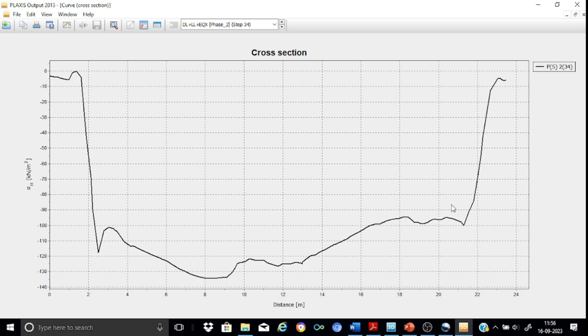So this is how we need to interpret the results in terms of the stresses as well as the settlements for the various phases, and then find out whether these calculated values match with our design regulations. If not, we need to change the various parameters, for example, the raft dimensions. We also need to inspect how to improve the soil properties where we find that the settlements are excessive. In this case, the settlements are of the order of, as we have already seen, 100 to 150 mm, and we have to compare with the maximum settlement that can be tolerated by this shear wall building.